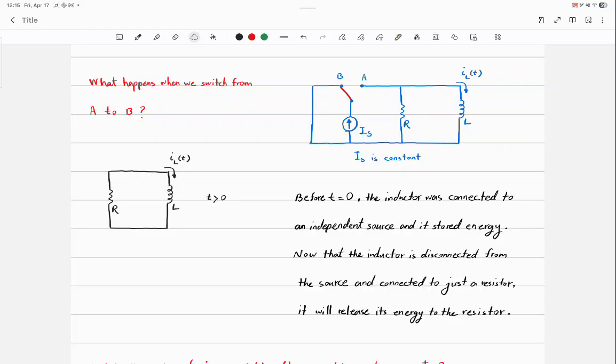Are you talking about the current source? Yes. The current source is connected to a wire, so the current will just go around. But it's not going to go to the right part of the circuit where I'm interested in finding the current. Oh, and you still have current though because the inductor stores charge. Oh, yeah, that was the next thing that I wanted to talk about. What I've covered so far is that I'm allowed to disconnect my current source from the part of the circuit that I'm interested in because they are not connected, because the switch has changed from A to B.